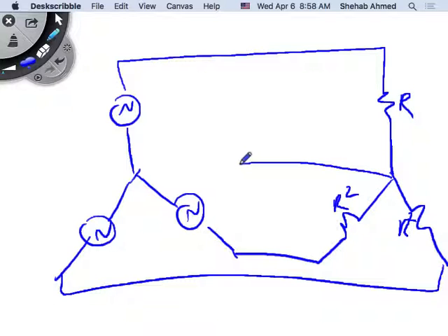What does that mean about this connection? That we will have neutral current. If these currents are unbalanced, that means the sum will not equal zero, and I will have current flowing in my neutral. Right? Typically, these circuits can be far away from each other. So the way we would typically connect them is actually,